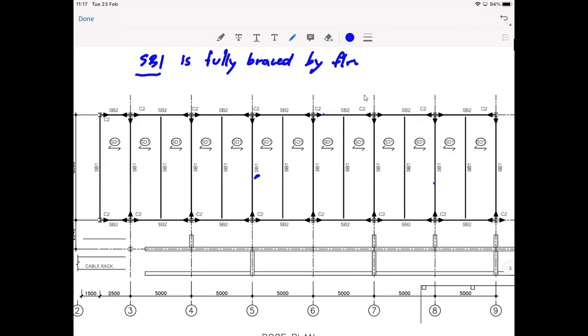And you know by now that your loading condition should be like this, right? That's your tributary width. And you could just go directly and compare, and you should use ASD. Please, there's no need to do LRFD, okay? Just ASD for both columns and beams and stuff, okay?